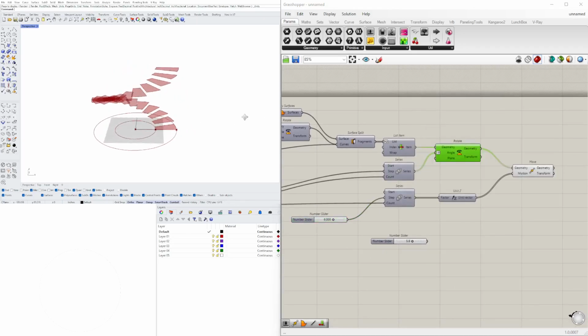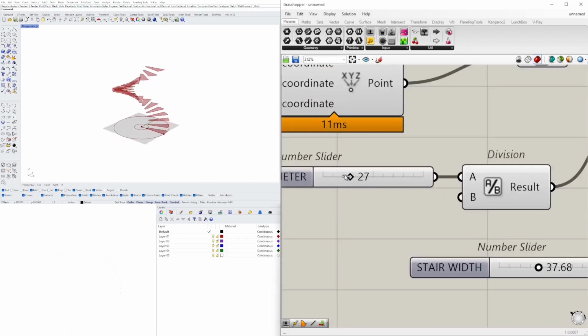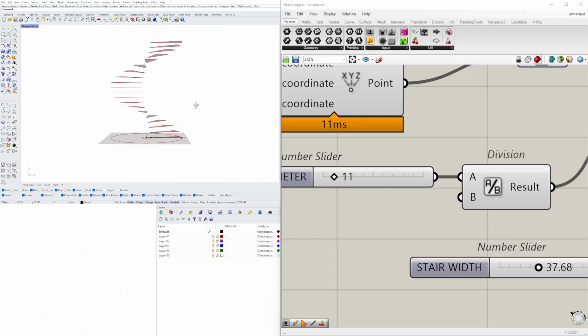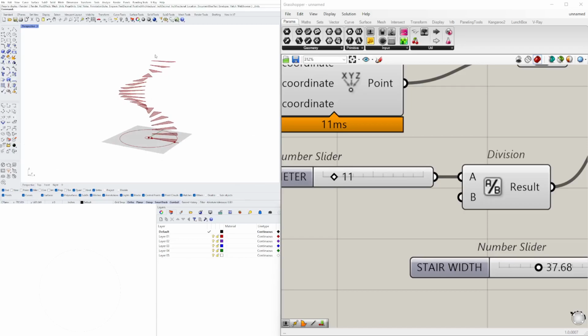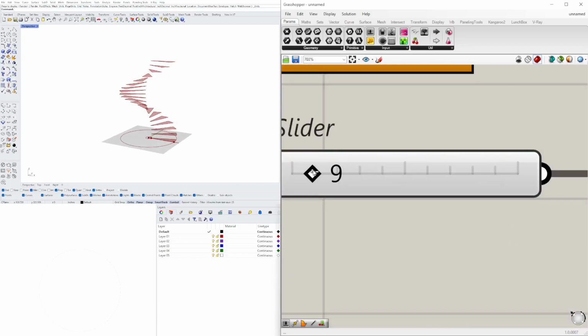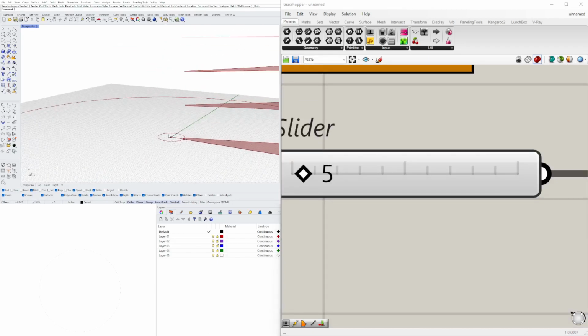Disable preview. Now let's go back and look at our dimensions. So our inside diameter, if we have it at 0, it will not work. So you would have it at a very small value, and regardless, let's say if you had a spiral stair like this, well, sometimes you would actually have a structural column going up here, and that's what supports these treads. So you would always have a small amount here. It wouldn't actually go to a point. That would structurally not work.